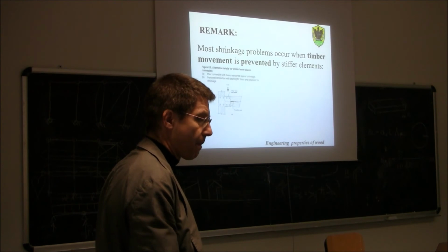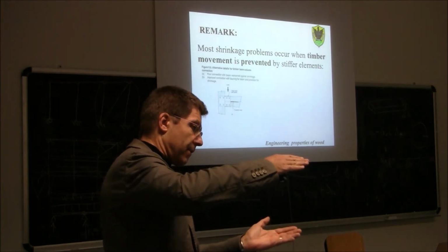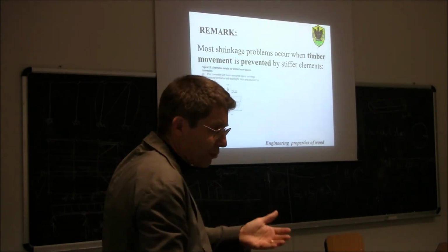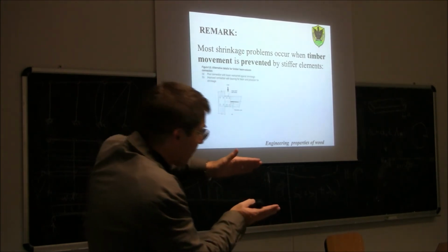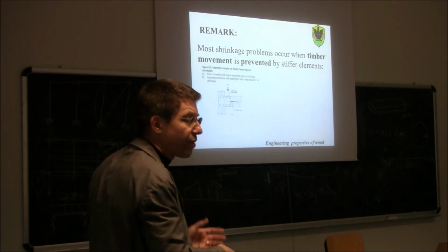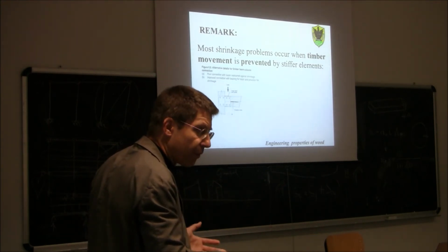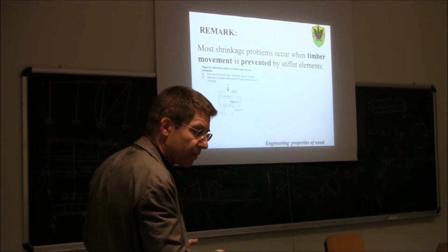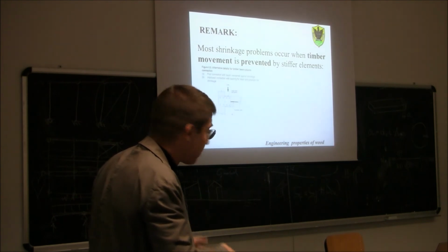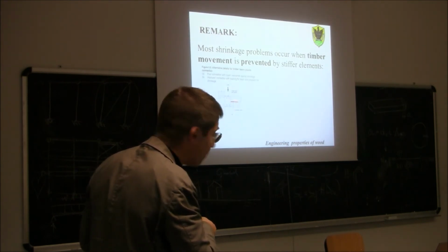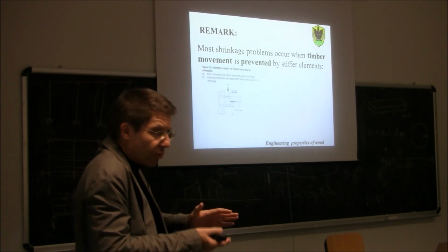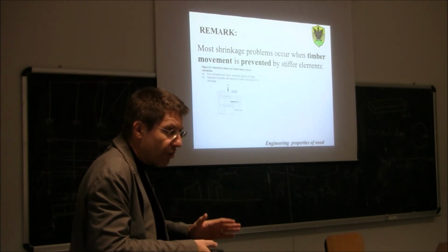The fiber should compress and... Exactly. So because of that there should be some shrinkage. So we would expect a shrinkage in this direction here. Can the shrinkage occur freely without any stress? No. Why can it not occur? Look here, there are some bolts and some stiff steel plates. So the shrinkage cannot occur because it's blocked by the steel.